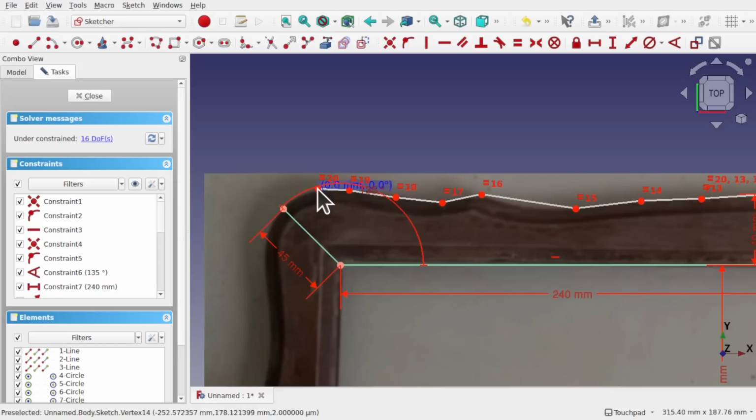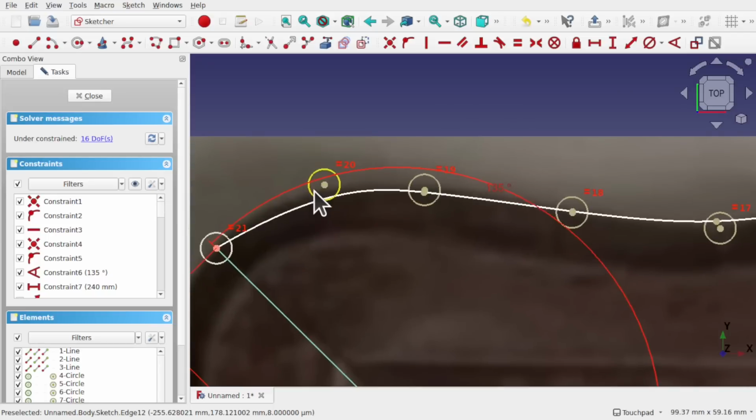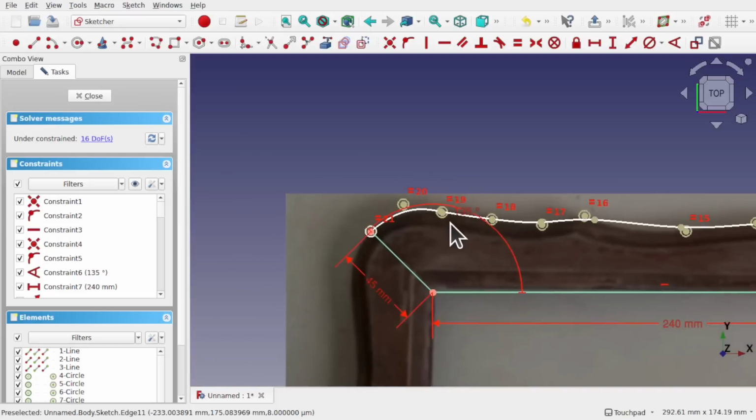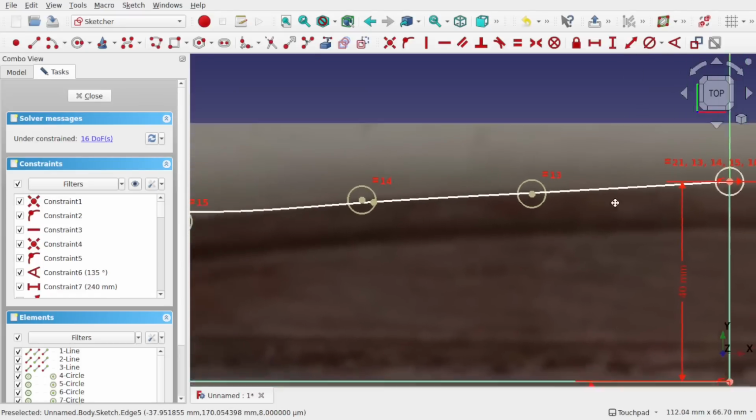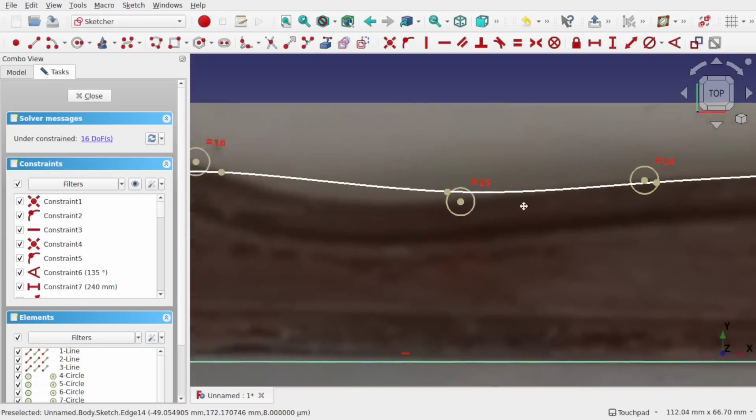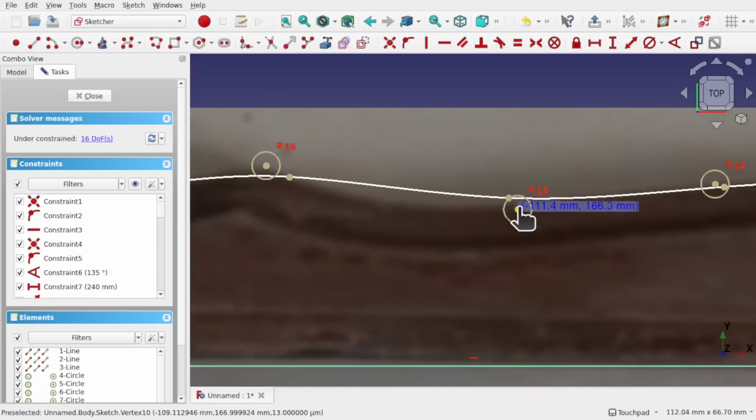And I can see this starts to curve down this way. So I'm just going to connect up with this one. Connect up. Right click to cancel. The B-spline takes effect. Right click to get the mouse pointer back. And then we'll tweak this B-spline into place. And I'm going to start over this side. And we're looking good here. That's more or less how I want it. This can come down a bit.